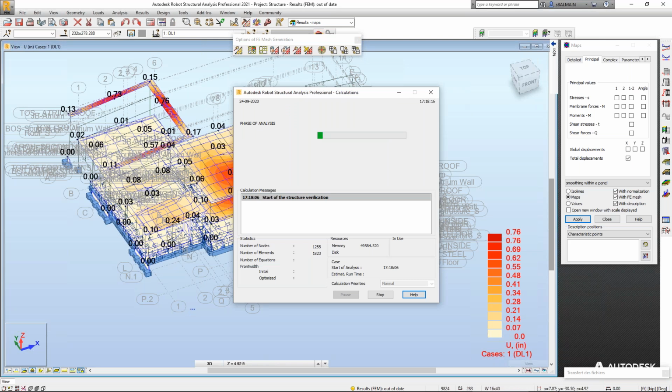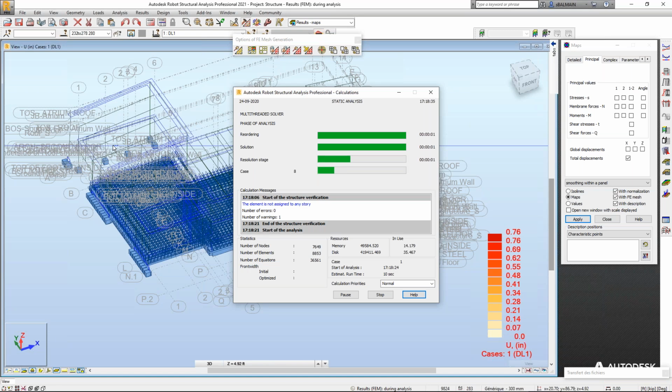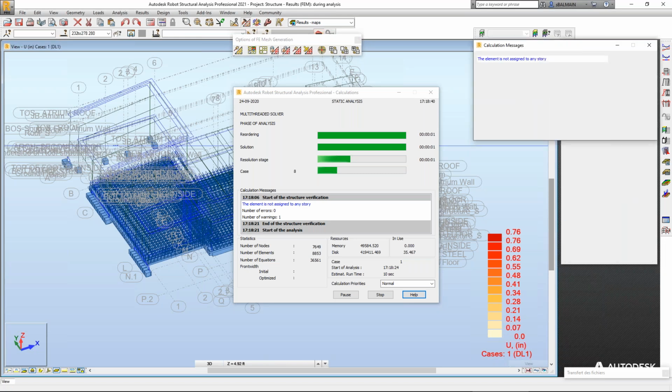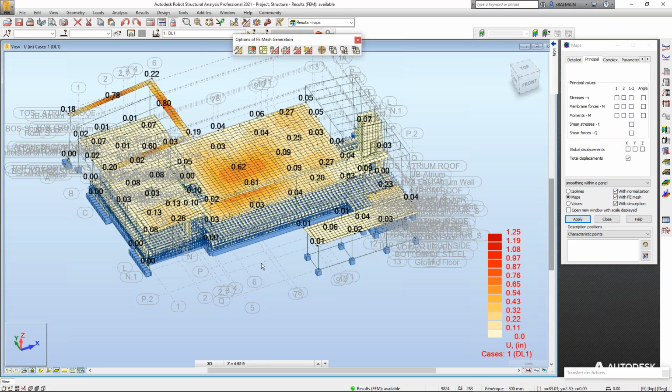In fact, what I don't like here, I have a column, and I want to have a lot of integration points to have correct results about this, to see the correct bending moment. And usually I have a question when I give lessons in management school: how do I know it's precise enough? And my answer is, you could have a very mathematically precise answer, but if after, from a rebar point of view or steel point of view, you don't change the real rebar reinforcement or you don't change the profile, it means you have the good one.